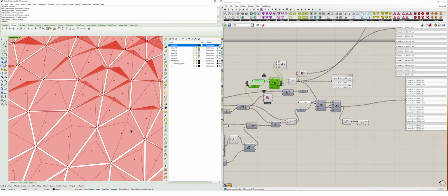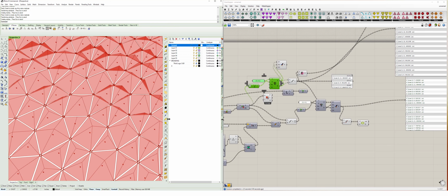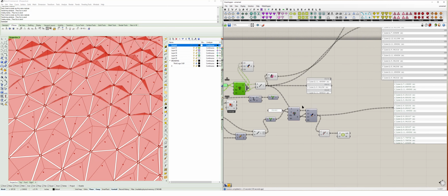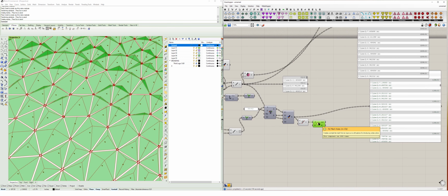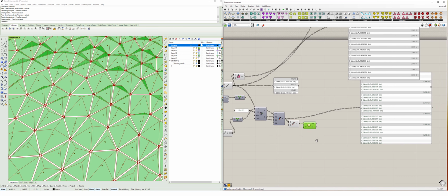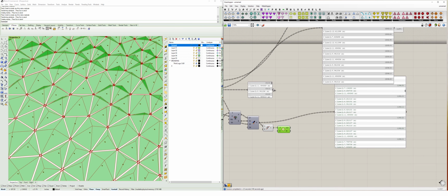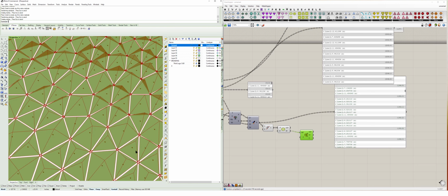In that case there's 4 meshes here to create that panel, and those merge together. We join the curve into a closed poly curve, and then we do that same fill mesh holes to create our closed meshes. Finally, we could also do a mesh join, and plugging these meshes into this input, it's going to create a single mesh per panel.